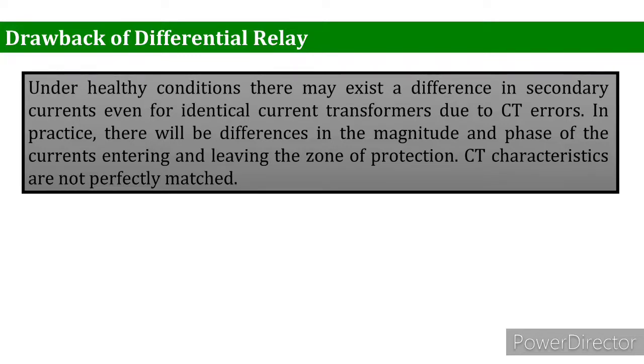Similarly, under severe fault condition, the current transformer may saturate and cause unequal secondary currents. If this difference exceeds the relay pickup value, the I pickup, then it may cause an unwanted tripping of the differential relay.